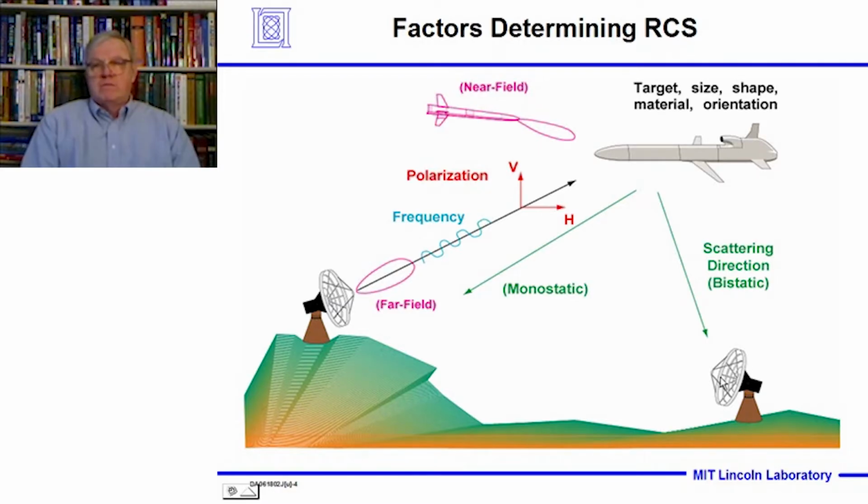You can remember from the first lecture I showed you that example of that World War II radar, the Chain Home system, that had one set of towers where the transmitting antennas were located, another set of towers where the receive antennas were located. That's a bistatic radar system. There are bistatic radar systems that exist right now. Most of them are monostatic.